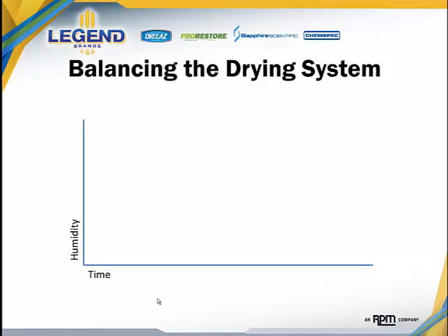Now, looking at this on a chronological timeline in a drying environment, generally when equipment is first installed within the space, humidity is going to increase. If you remember from our earlier discussions, this is because we're tackling the easy water, the surface water, and this water evaporates at a very high rate. As that water evaporates, humidity will build. However, this spike in humidity, as it's commonly referred to, should be very short in duration. If things like the water extraction and other preparation and mitigation tasks are performed properly, this spike should be shorter than 1 to 2 hours in period of time.